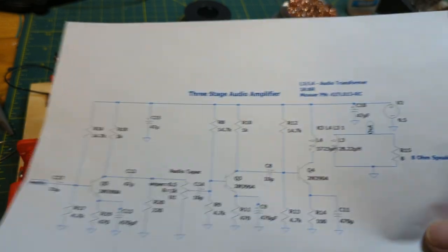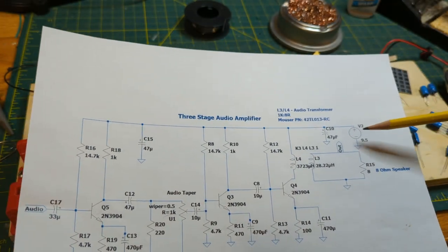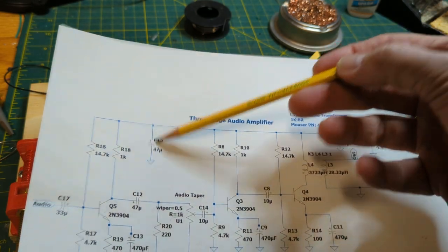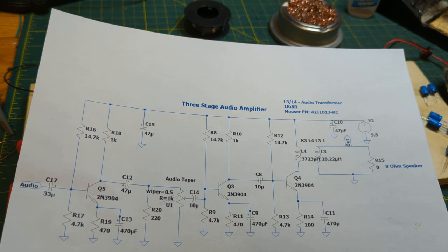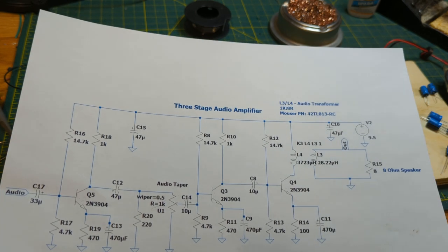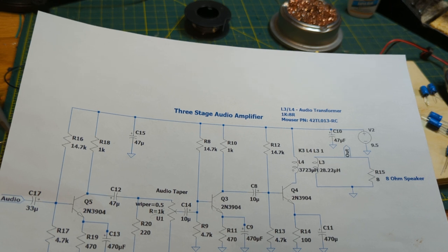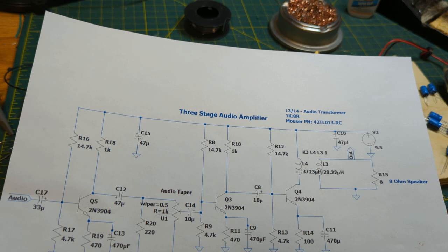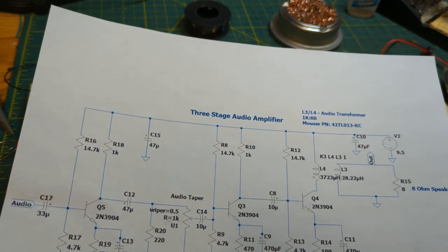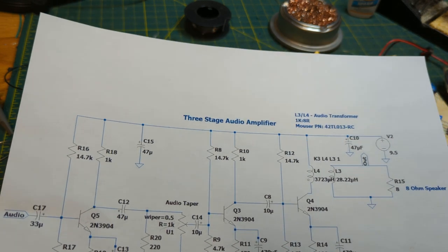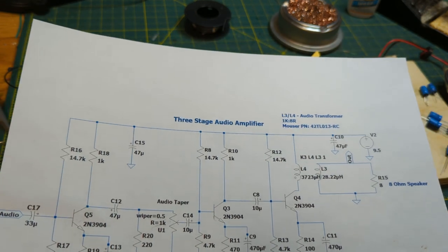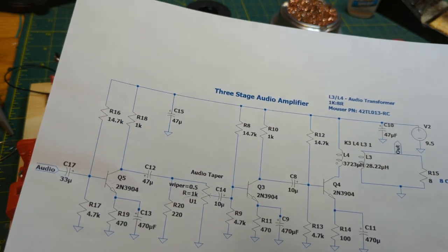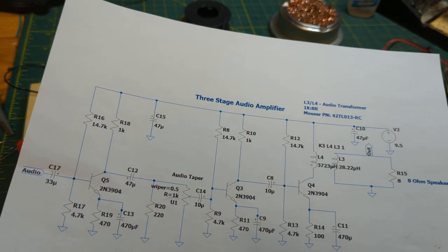So that looks like we're going to bring in our 9 volts, and we're going to have two 47 microfarad caps on there, and those are just to bypass any RF, any audio that happens to be hanging on the 9-volt line, so that it doesn't get into our circuit. So that's what those are. Those are bypass caps that are going to bypass any audio frequencies to ground. So we don't want any audio coming in over the DC power rail.